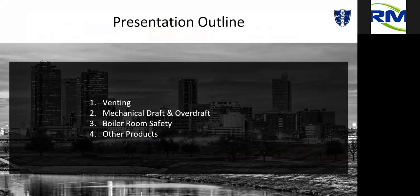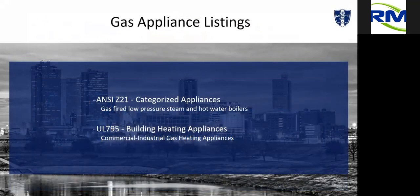So when it comes to venting, basically a manufacturer has 2 choices when it comes to getting their products listed. First option is they can be listed as an ANSI Z21 categorized appliance. The other option is to be listed as a UL 795 building heating appliance. Now, very general rule of thumb, if the burner is built into the boiler, it all comes pre-packaged, it's most likely going to be an ANSI Z21 appliance. That's your RBI type products.